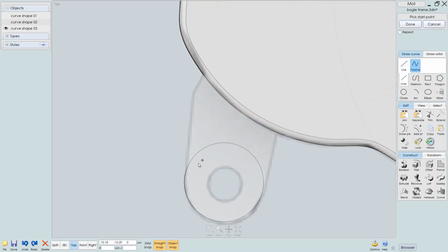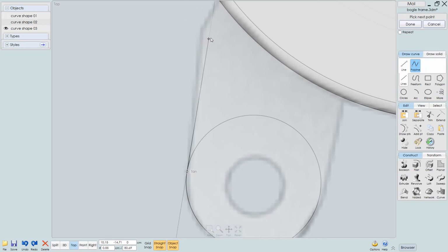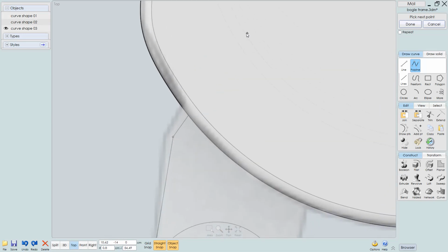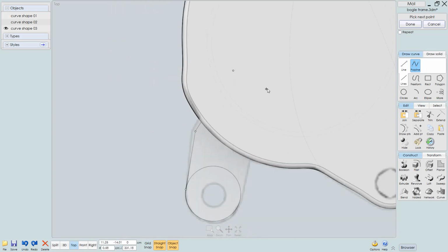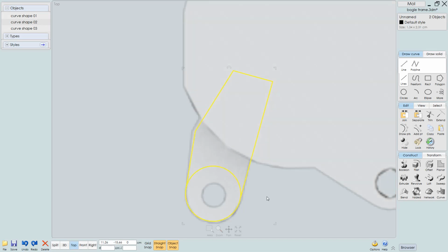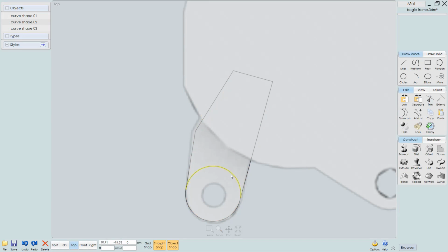And then I'm going to use the polyline, snap to this point here. And I want to move it along the tangent for now. Maybe we should start at a different position. Let's start about here. And do something like this. I'm going to move this inside of the object. And let's see. I'll create a construction line here and then create 2 points here. Right click to confirm that. Just isolate these two, trim them, remove this part and join these two.